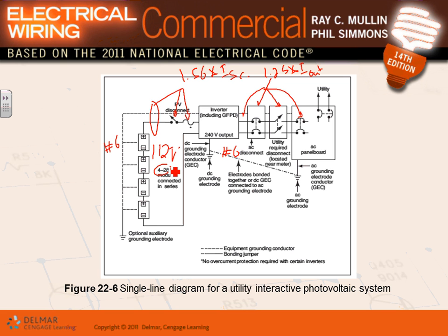Any comments, guys? Any questions? This applies to us, guys. The colder the weather, the more voltage the panels will generate, believe it or not. So there's a bunch of tables, guys, that allow you to modify this voltage based on the temperature. In Minnesota, it was -2 today. You go to -2, there's a table that will tell you. The lowest temperature encountered in Minnesota, say -25. Based on this lowest temperature, the voltage will be sized. They call it open voltage for the panels, multiplied by a factor. I'll show you in a second.